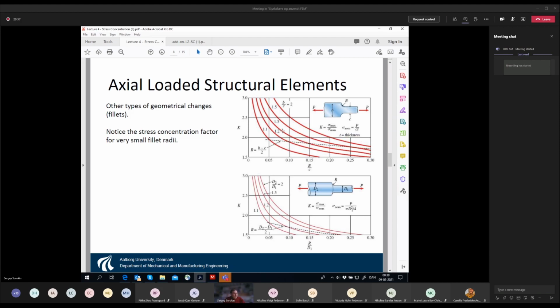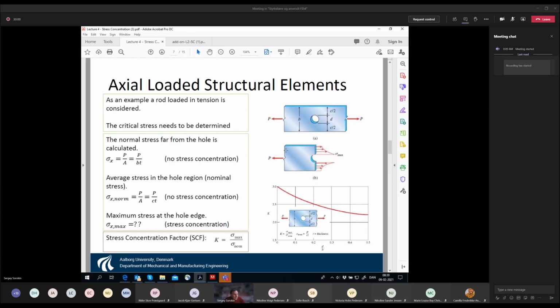Yes. So now if you just let me go a little bit back here, then what actually happens is that, let's now think about the concentrator not in the shape of the circle, but now let's say that we have an ellipse, so that we maintain this diameter, this width, the same, it's a D, but we just squeeze this hole a little bit towards this axis.